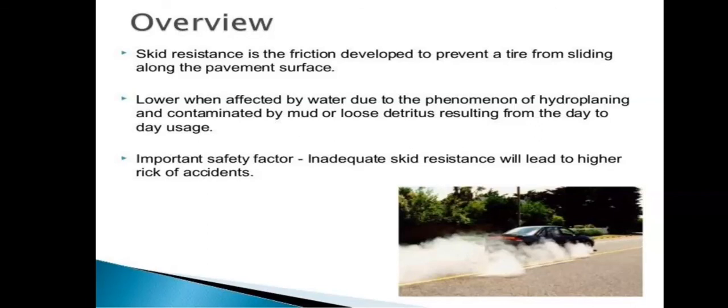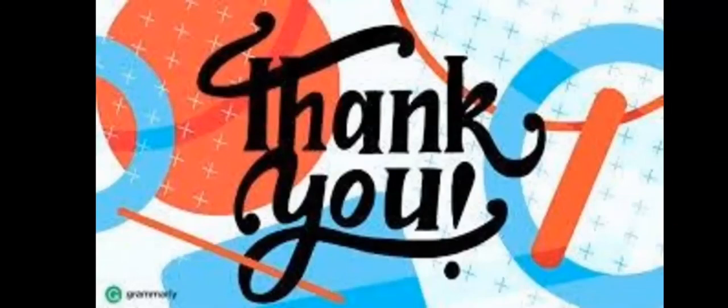Overview. Skid resistance is the friction developed to prevent a tire from sliding along the pavement surface. It is lower when affected by water due to the phenomenon of hydroplaning and when contaminated by mud or loose detritus resulting from day-to-day usage. It is an important safety factor; inadequate skid resistance will lead to a higher risk of accidents.